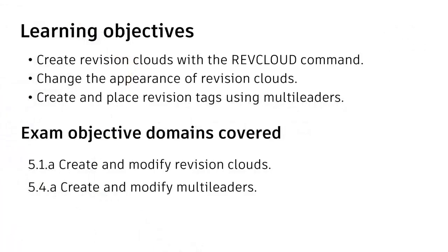I'm going to be reviewing different markup tools available inside of AutoCAD. I'm going to be marking up a drawing using the RevCloud command. And I'm going to use the multileader tool to add a revision tag to the RevCloud.